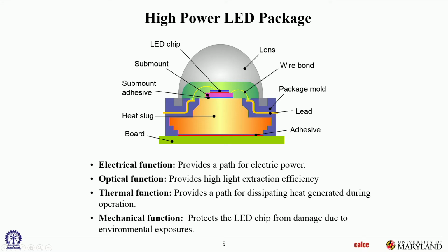Okay, so what degrades over here? All the standard suspects. The die attach is a problem. The wire bonds are a problem. The attach further below between the heat slug and the substrate is a problem. The lens is a big problem.